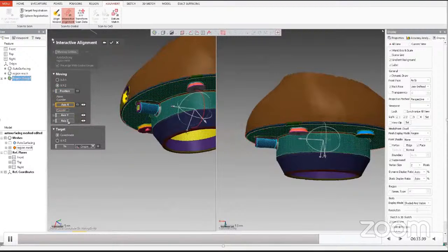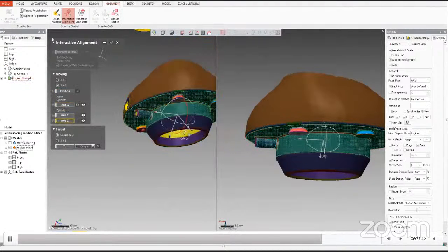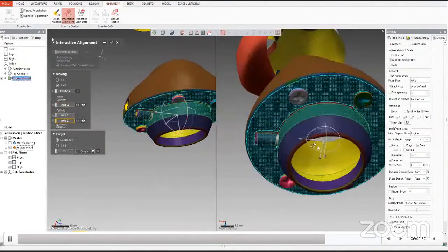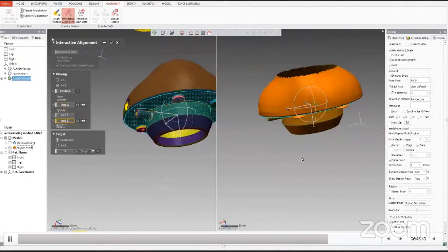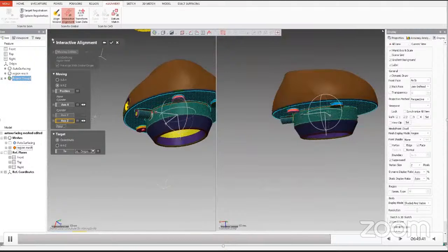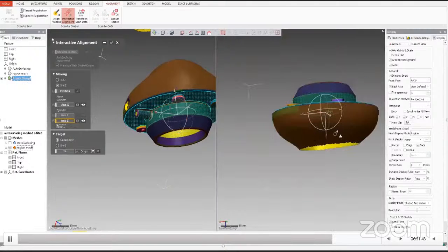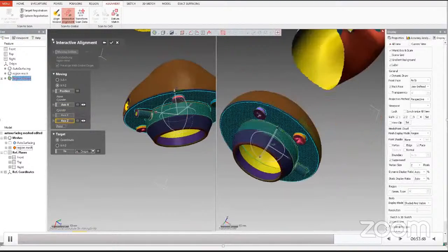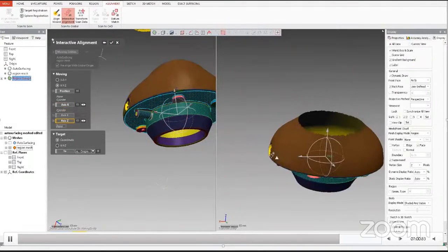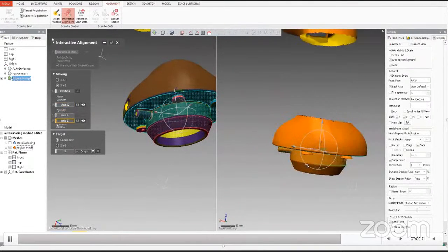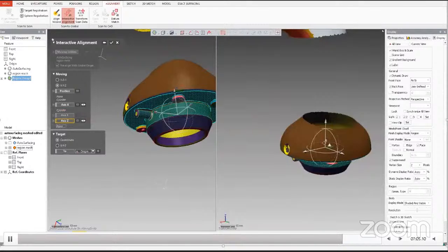Now we can select the z-axis, which I want to make in the upward direction. So I will select the plane at the bottom, this one, and we will see that the z-axis is now normal to the plane, so it's going toward the down. I want to make it in the opposite direction. So I just click on the arrow and the z-axis has been shifted toward the top, which we can see on the right-hand side screen. So the x-axis is along the tube and the z-axis is normal to the bottom plane. And the y-axis direction is perpendicular to x and z.